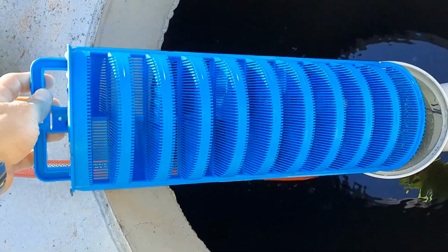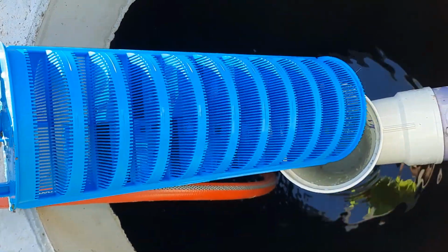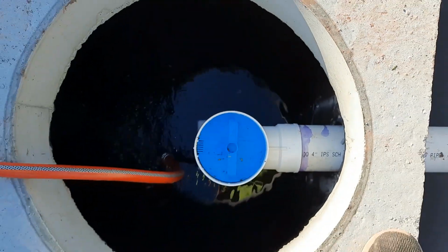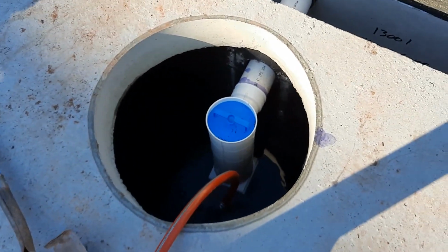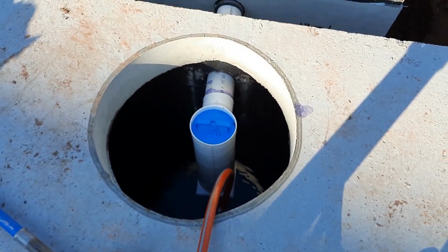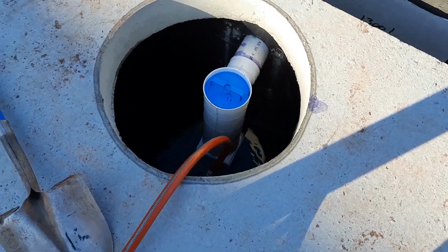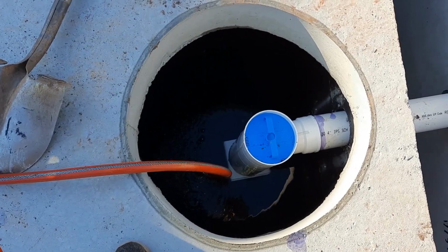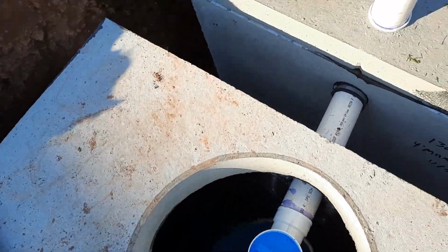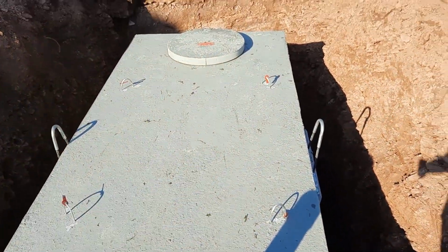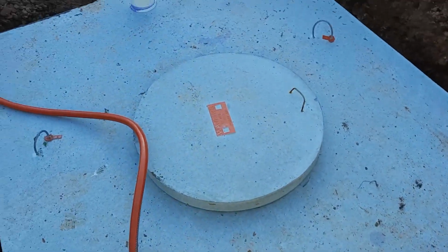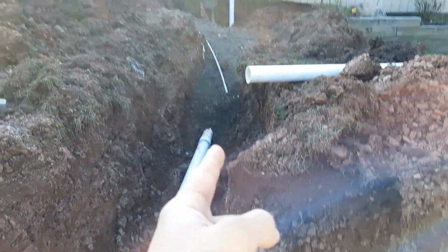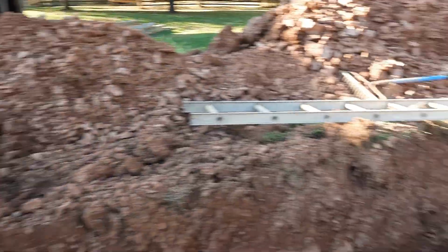All right. This device just kind of filters it a little bit better as it exits the septic tank. And it's required for most of the towns that we service right now. It might be a state requirement, actually. What they're doing now is they're filling up the tank just to make sure that there's no leaks or anything like that. I imagine it might also be to fill up the pump tank, which we'll need for the pump test later on. All right, you can also see this is an inspection port here. You can see the line that goes out and it runs out to the house and connects over there.